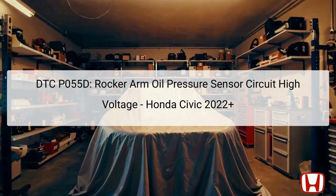The DTC P055D indicates a high voltage condition in the rocker arm oil pressure sensor circuit for the Honda Civic from 2022 onwards. This code is triggered when the output voltage from the rocker arm oil pressure sensor exceeds a specified threshold, signaling an abnormality detected by the Powertrain Control Module (PCM).